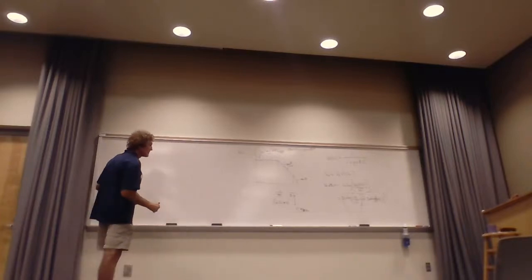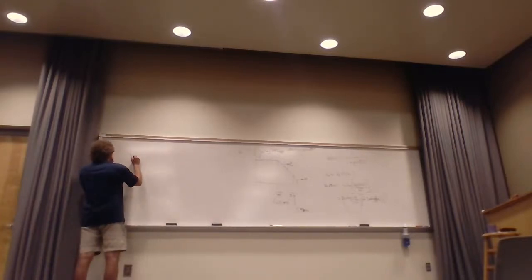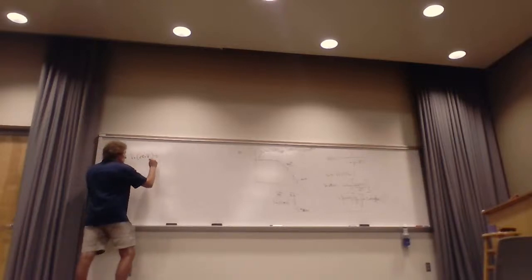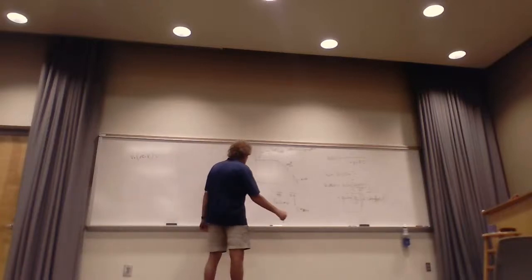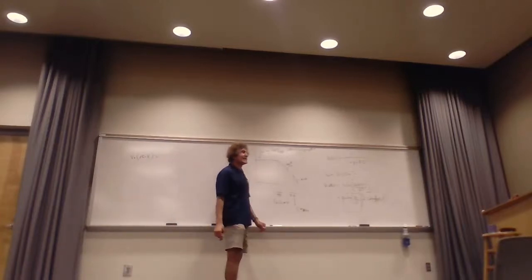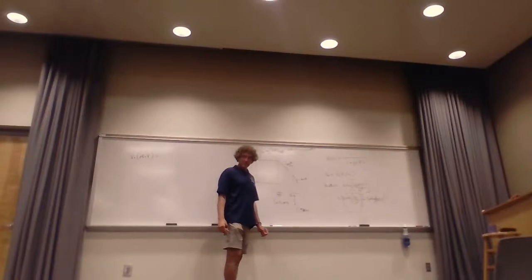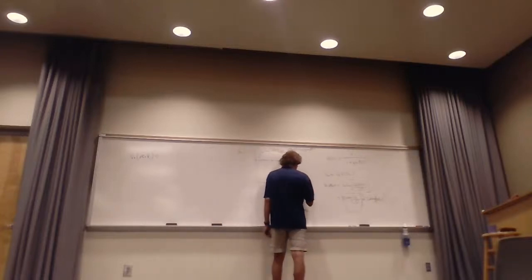So when I look at my V out in dB microvolts, first, I'm going to find out what my V in, or V source, is at that frequency. Got it? And it's the ninth harmonic. Since the characteristic frequency was 10 megahertz, the ninth harmonic would be 90 megahertz, right? So I'm way out here.